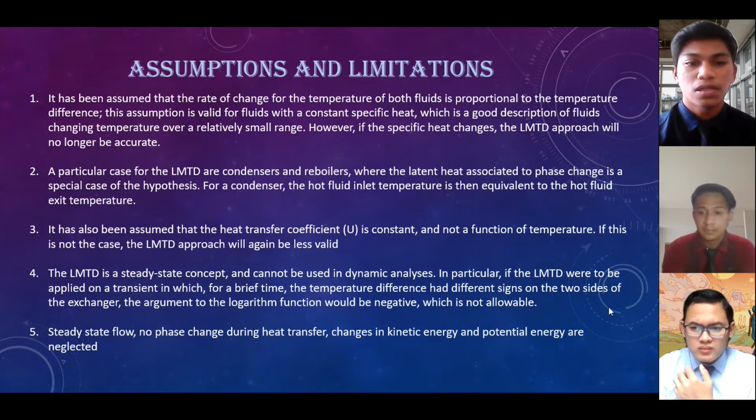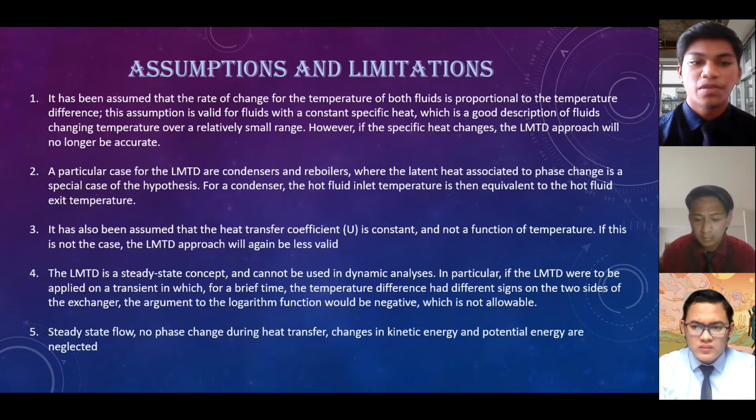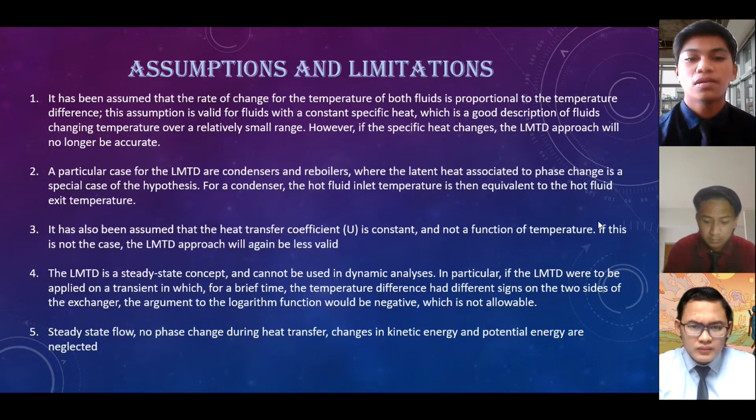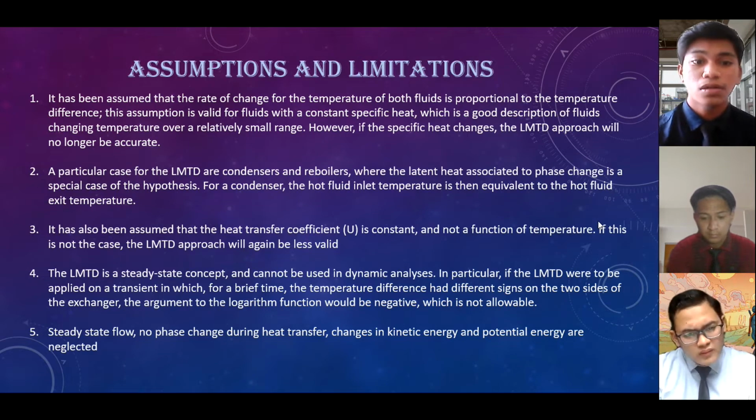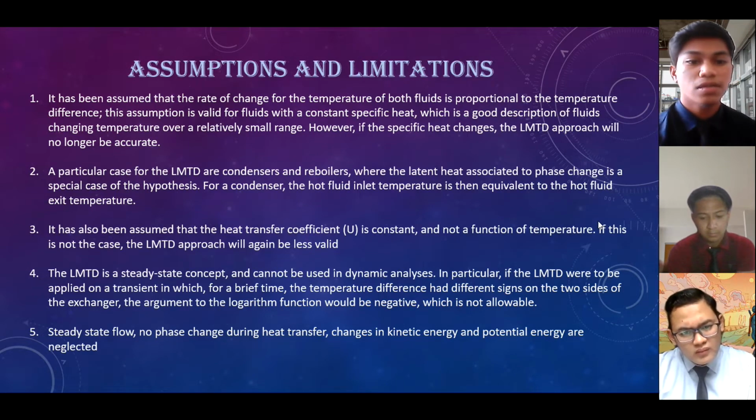In particular, if the LMTD were to be applied to a transient in which for a brief time the temperature difference had a different sign on the two sides of the heat exchanger, the argument to the logarithm function will be negative, which is not allowable.